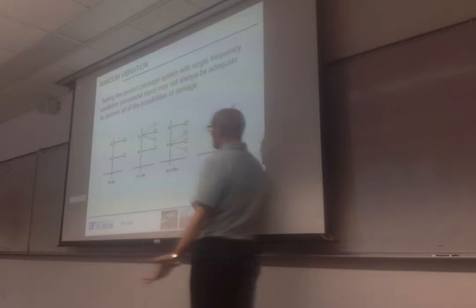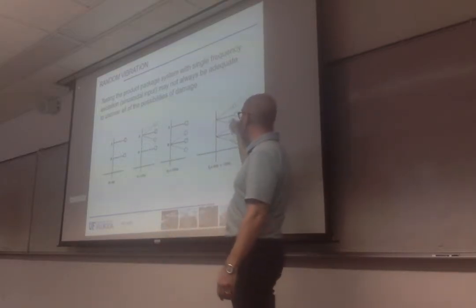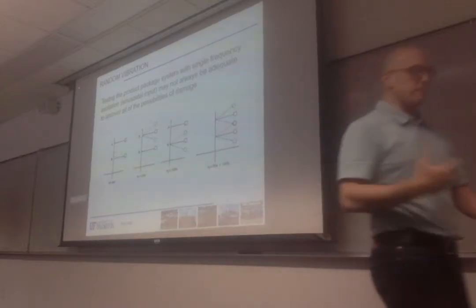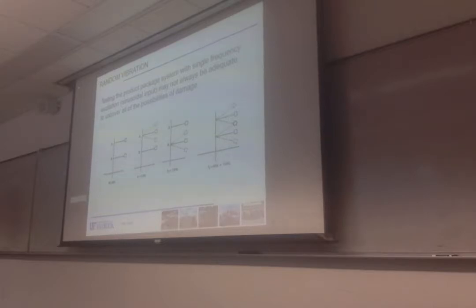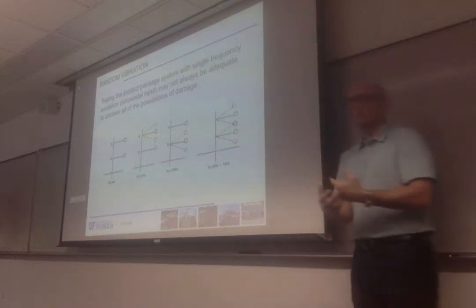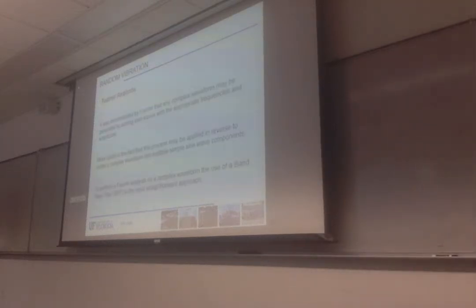But if you were to impose on the system a combination of those two frequencies, what you may get is damage. So the combination of many frequencies sometimes will result in damage that you may not see if you just vibrate at a single frequency. So that's why it's good to look at natural frequency, what they are for your package, stacks, your product. But in the end, what really is important is you look at how your product or package or pallet is going to behave when you expose it to a combination of all of these through random vibration.